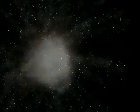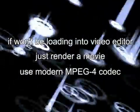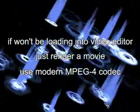If you won't be loading the rendered movie or images into another application, such as your video editor or compositing app, then you may just want to render a movie file. Choose a modern codec that gives you decent quality, something that provides MPEG-4 compression like DivX, XVID, or any of the other MPEG-4 codecs available.